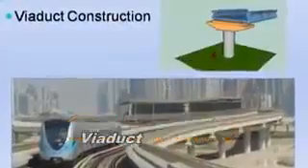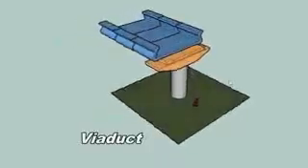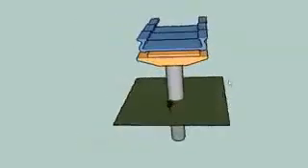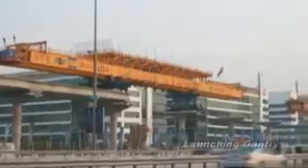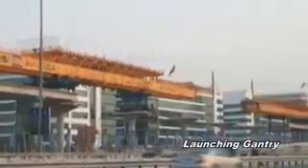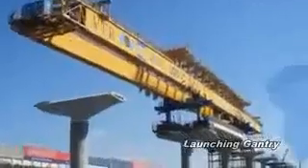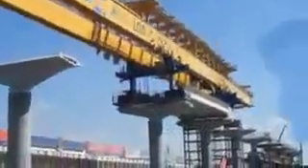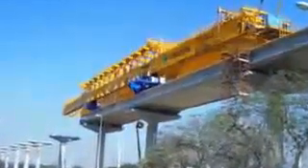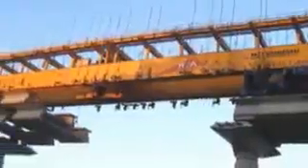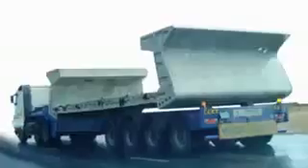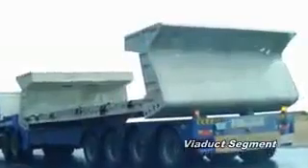Metro. The viaducts were constructed using the span-by-span method with U-shaped precast concrete segments, erected using a self-launching gantry. Average span was 45 meters. Segments were 10 meters wide by 4 meters long and weigh 55 tons. The placed segments were post-tensioned and the cable ducts were grouted.